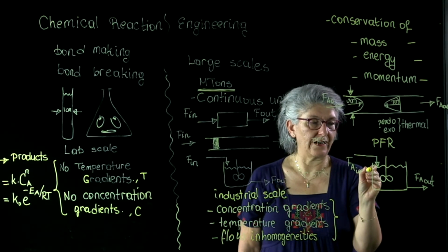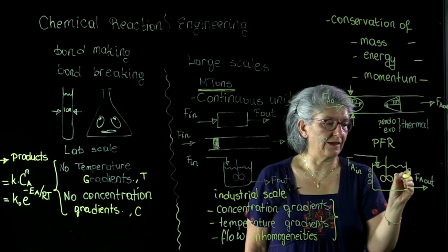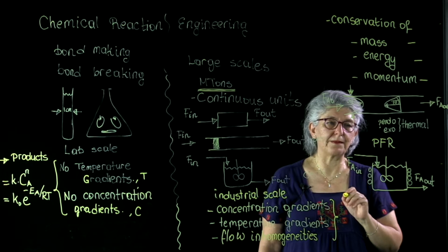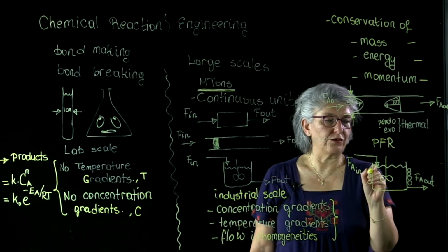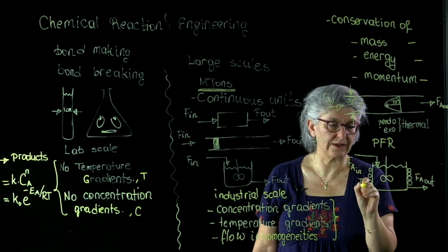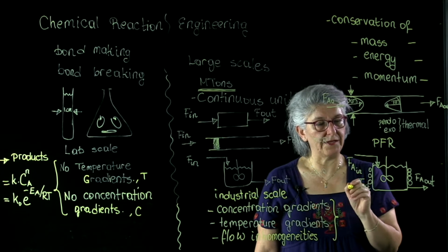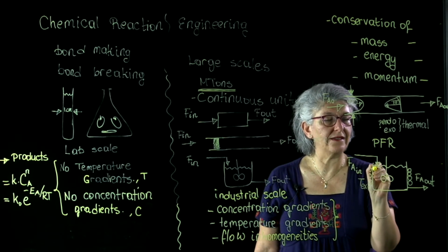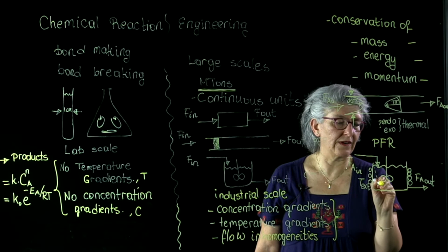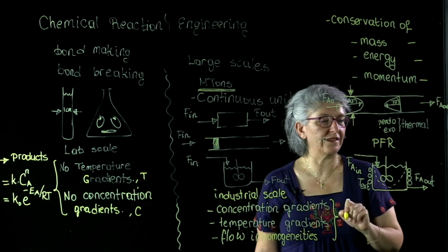If this reactor is externally heated using a heat mantle or serpentines, we are going to have an external temperature provided here, and if there are imperfections in the mixing, we will have gradients of temperature that are going to have R versus T functionality, as you would see.